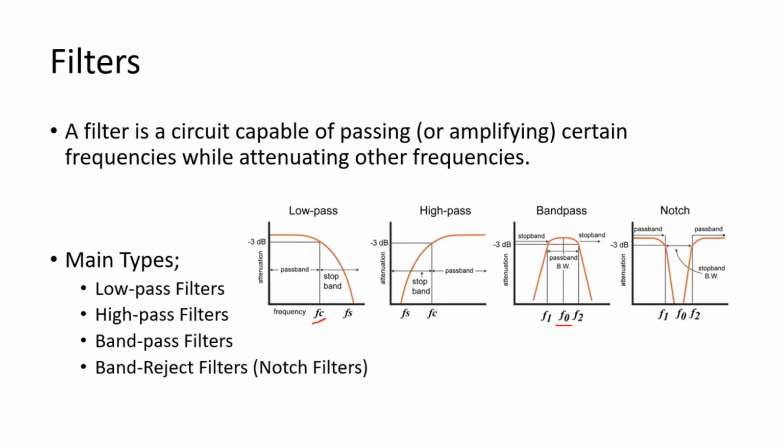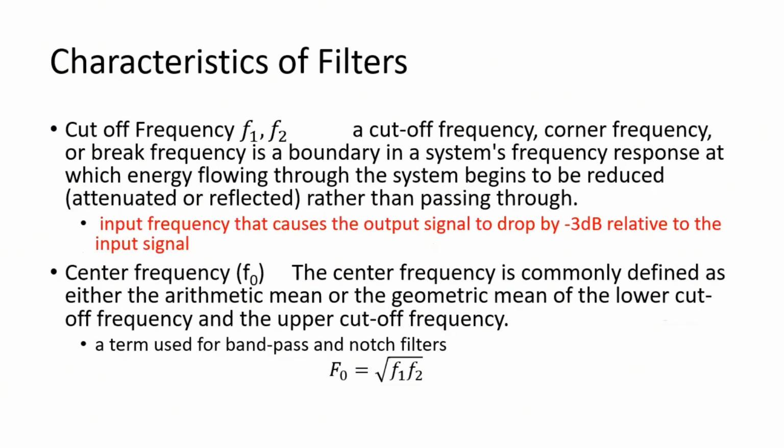Here the cutoff frequencies are F1 and F2. So what is the cutoff frequency? The cutoff frequency, also called the corner frequency or break frequency, is the boundary in the system's frequency response at which the energy flowing through the system begins to be reduced, meaning attenuated, rather than passing through.